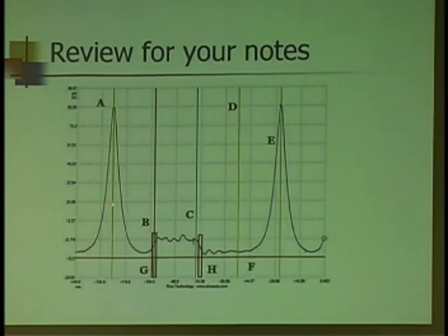As I move down, nearing bottom dead center of the power stroke, the exhaust valve is going to start to open, and that upward ramp should occur right about BDC. Should be right about the middle, give or take 10 or 15 degrees. If there's a timing issue, if we're off a cam tooth, you're going to see that shift at least 10 or 15 degrees more than what it should be. So you'll see it. It won't be a question of whether it's just a little bit.